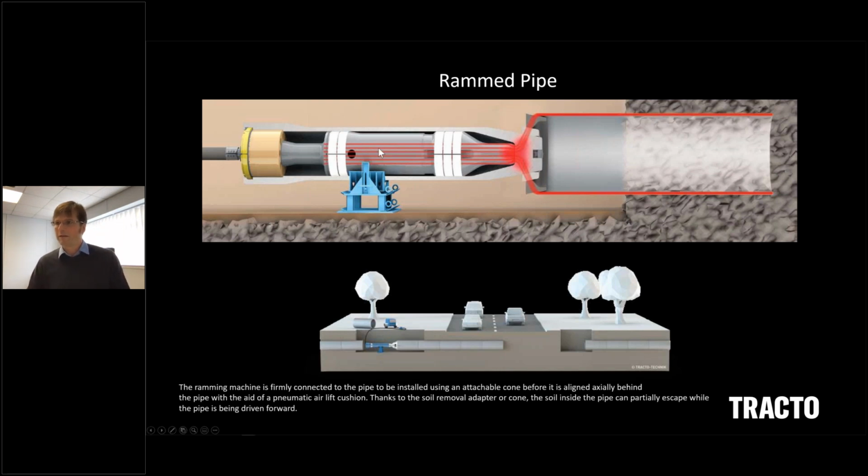The piston and the front end chisel obviously slam into the front end of the rammer housing, generating forces that are transmitted through the conical front of the machine into the ram cone, and then along the cutter segments. These are really responsible for making sure that this energy is transmitted in a linear fashion into the product pipe.